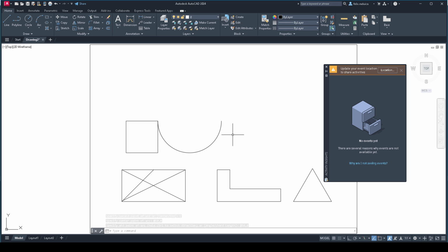If you want to draw it the other way around, you repeat the arc command, then snap to this point, then you give the center point, so you have to select it. And now you select the angle. And you give the angle. So the angle will be opposite if you want to draw it like so. That means minus 180. And this is how you draw an arc.